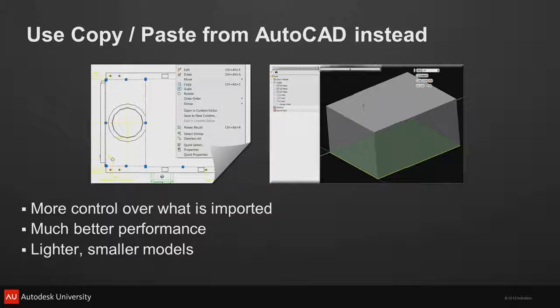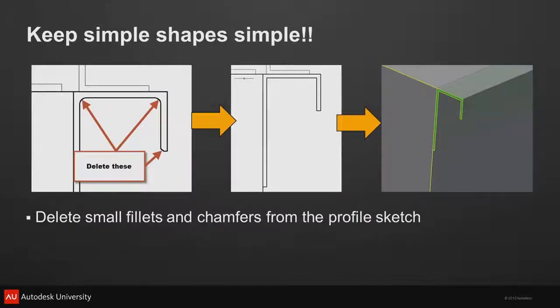And that's exactly how these things work. So remember, you always got to keep that in mind. Keep things as small and compact as you can. It's just kind of a rule of thumb. And I think I'm kind of beating a drum there. It's something we've known with AutoCAD for a long time too, right? Just kind of keep them small. We've all gotten lazy now, right? Because hard drives are bigger and RAM is cheap. But that's going to run out of gas sooner or later, especially when you start talking about doing this stuff across the web, because now we've got another problem. We're talking about bandwidth. So we don't want to remove big chunks.